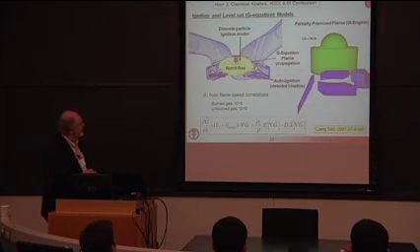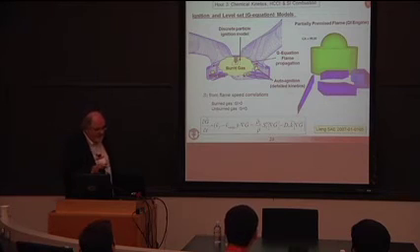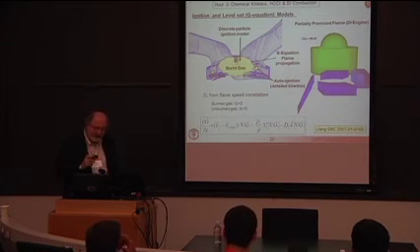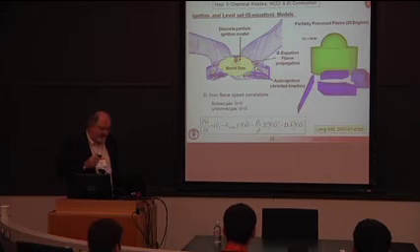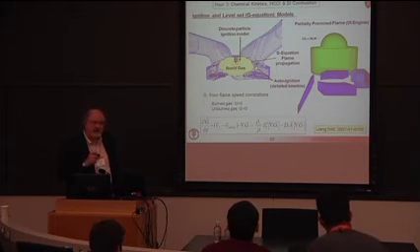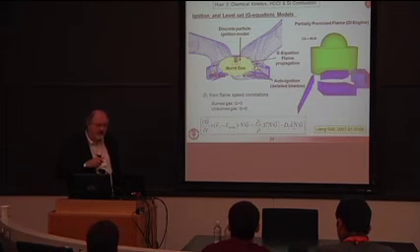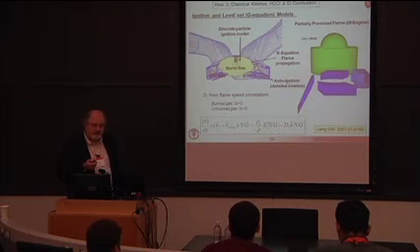How does this work? Well, basically, here's our spark plug. We use what we call a discrete particle ignition model. Now, why do we need that? A spark gap is typically very small, 10 thousandths of an inch, much smaller than the computational cell size in an engine. And the growth of that initial spark kernel cannot be resolved on a practical mesh.